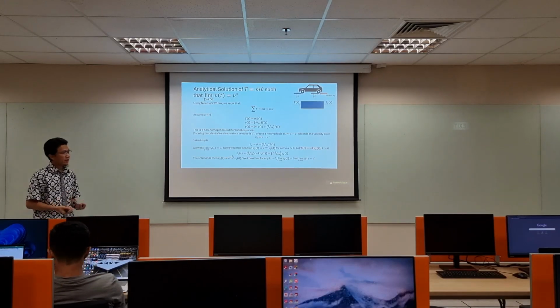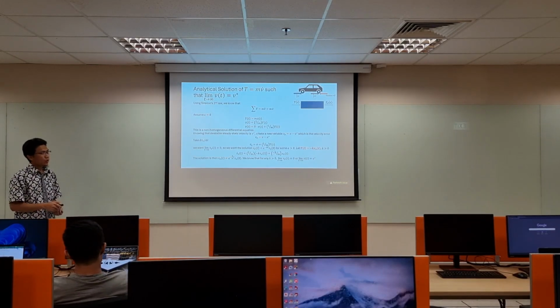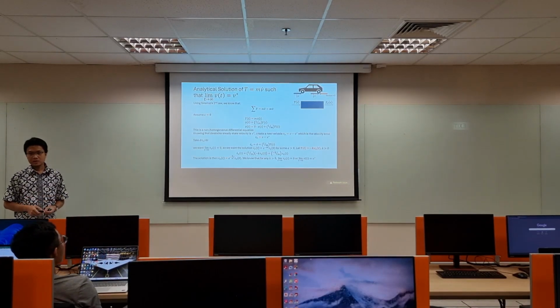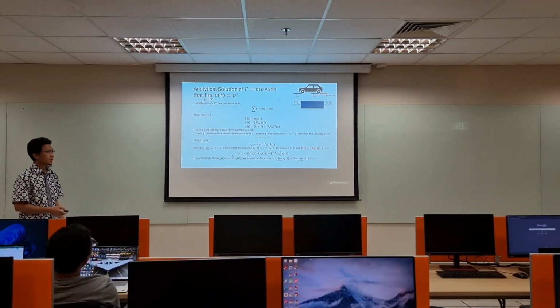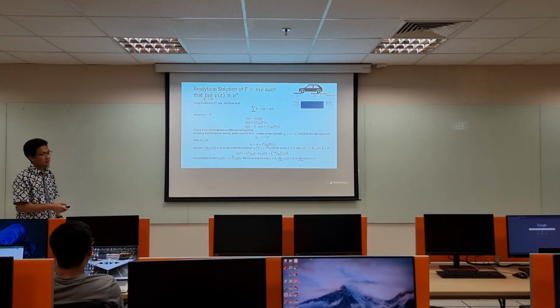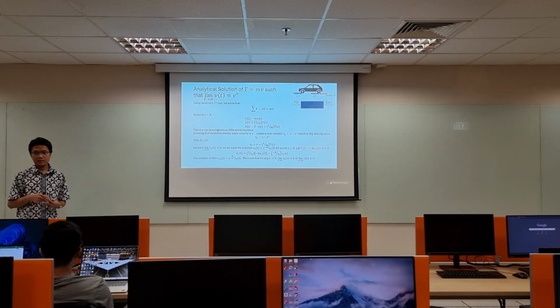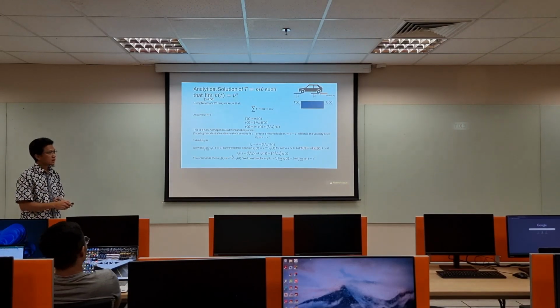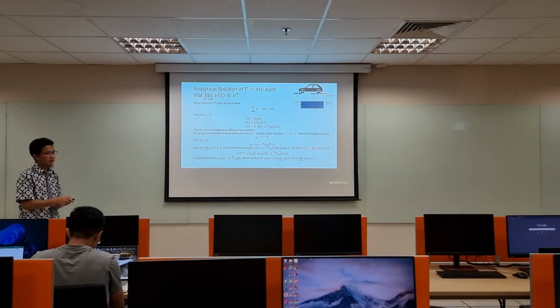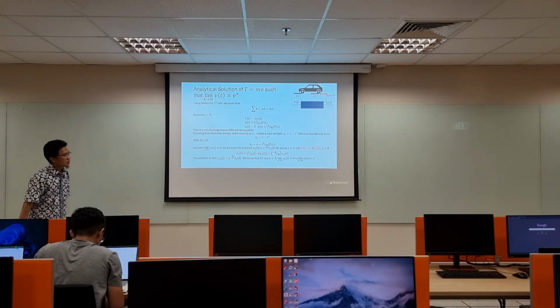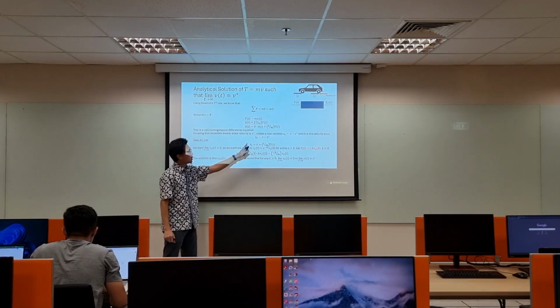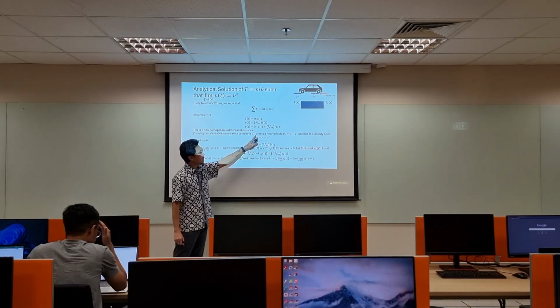Okay. The strategy here is that we create a new variable, which is the velocity error. The velocity error is defined as the current velocity minus the desired velocity, and then we just expand the dynamics of it. So what we do is we put the dot on the top.